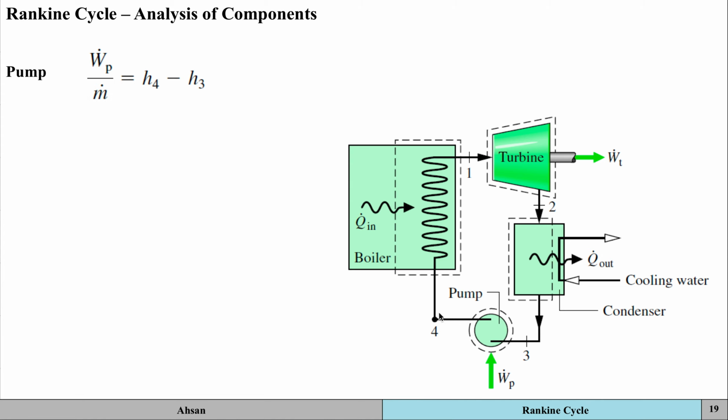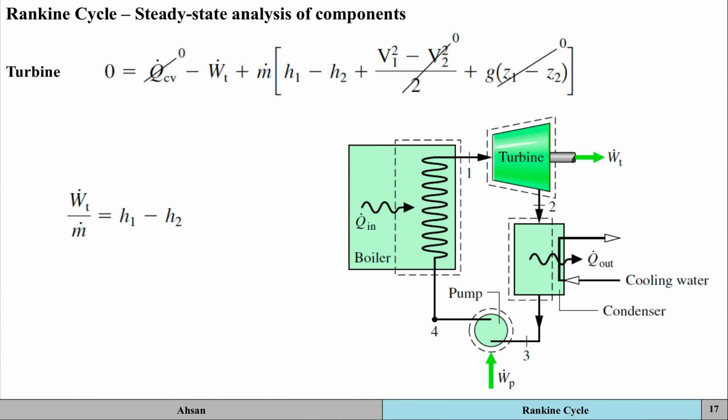And that is because, and this is a good way to remember the subscripts that you're going to use for the components. For work done, you're extracting work out. For a condenser, you're taking heat out of the system. So for these two, you're going to have initial minus final values.